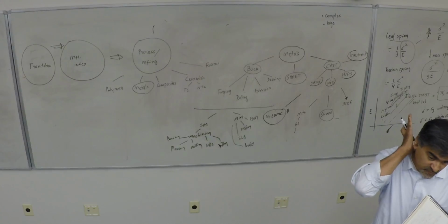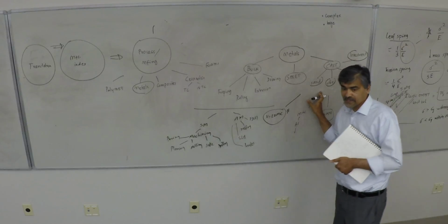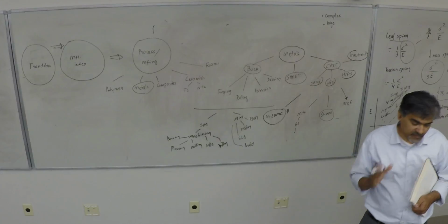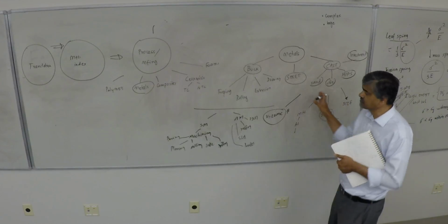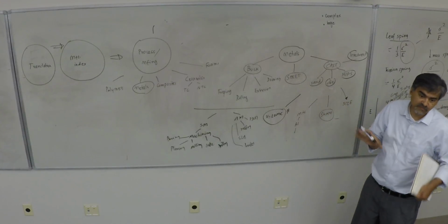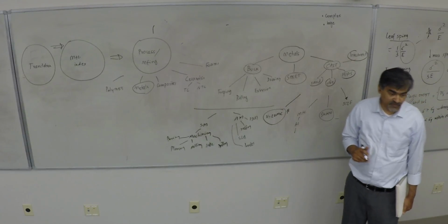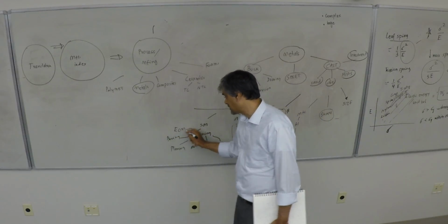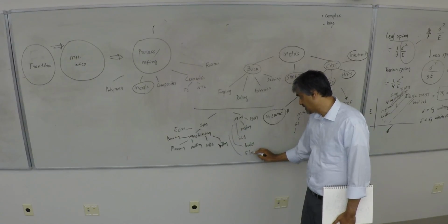Which one would injection molding fall into? Is that more of an additive type process? Injection molding is more like a sand, like a casting process, right? Where you're taking bulk, pellets or bulk material, and then filling the part through flow processes. So it's not necessarily additive unless you stretch the definition. It would be a flow process. Additive manufacturing would be like electroplating, something like that. Not ECM, that falls under electrochemical machining, but yes, electroplating coating could certainly be in that family of things.